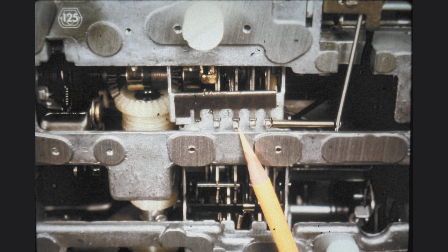Actually, these screws control the vertical rest position of the rear of the operational interposers. And due to the angle and the shape of the operational selector latches, the height of the rear portion of the interposers ends up controlling the horizontal front-to-rear position of the corresponding latch. Since there isn't any index selector latch, we simply adjust the rightmost screw to match the others.